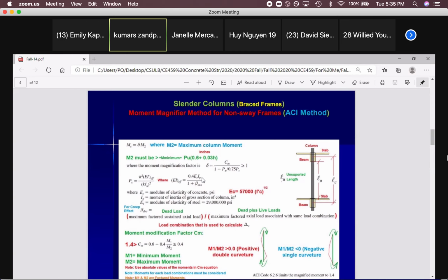Ig, what's Ig? Ig is for the column around the bending axis. Bending axis, I showed you one more time. I'm showing this. Please put a note for yourself. Yeah, please write something, because later you might not be able to remember this stuff. If your column cross section is like this, the column by itself is your bending axis. That's that easy. So for Ig, consider this b parallel to this one. And consider this your h.